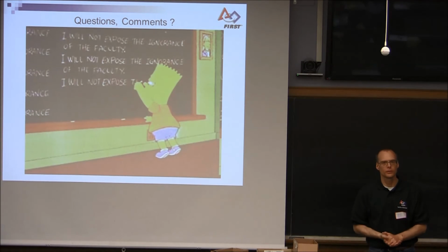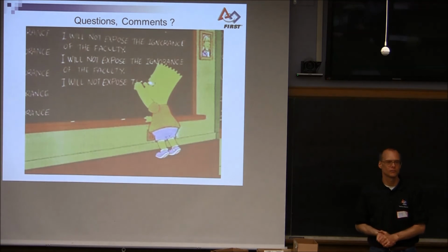And you can practice with that, and you'll find when you're doing those kinds of things, there's all kinds of little subtleties, like is your gearbox a little bit wiggly? Is the sensor mounted nice and firm? There's all kinds of little details like that you can learn lots of things from. Now, you don't have to build the entire robot.